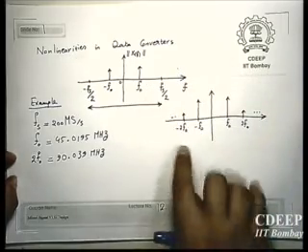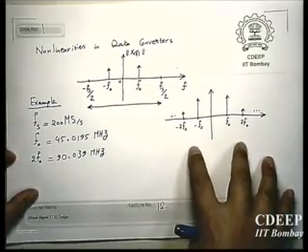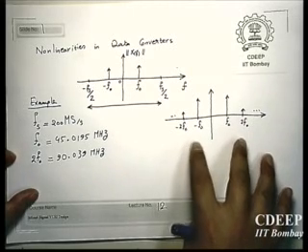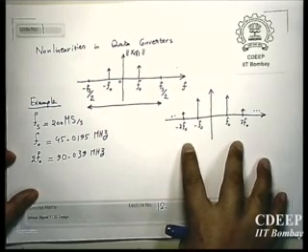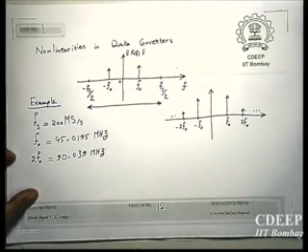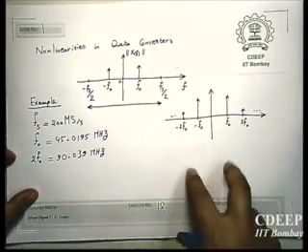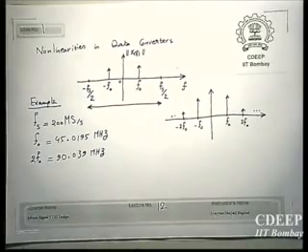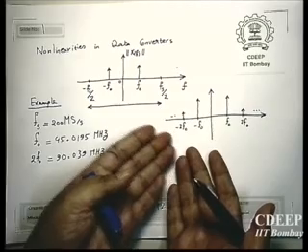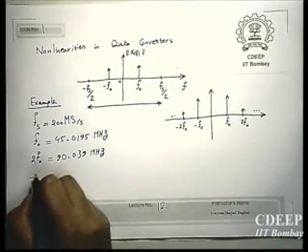Now if you have this signal and you sample it, there will be aliasing. To see what components of nonlinearity come into your band, you consider those components whose effective frequency, after calculation, lands here. You have so many components: from minus 2f0, minus 3f0 on this side, to 2f0, 3f0 on the other, out to infinity. So, for example, consider this component: suppose you have the minus 3f0 component.